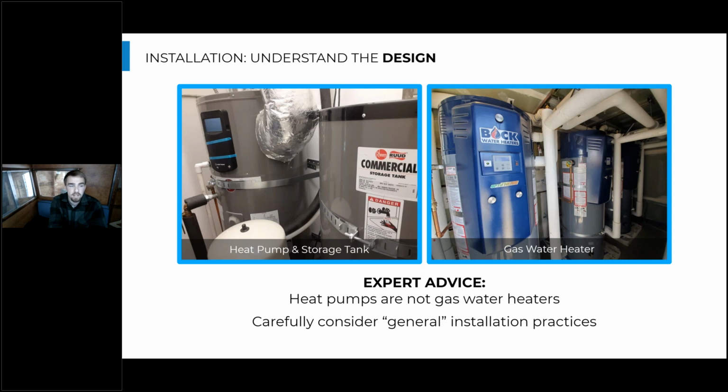That might include things like tank connections or maybe check valves on makeup water lines that weren't actually in the drawings. These have been practices that have been really successful in boiler installations that weren't completely necessary to talk to the engineer about during installation.